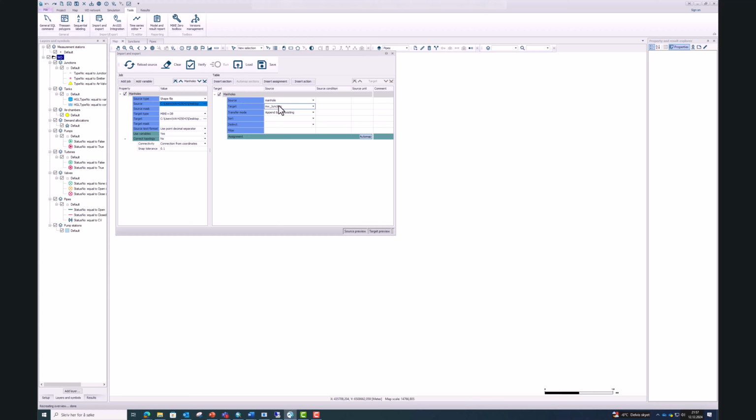in the model. So with this in order, we can just click AutoMap to get a starting point for the attributes from our shapefile that we want to give our model elements. As we see, the geometry is automatically mapped, and we need to map the elevation.